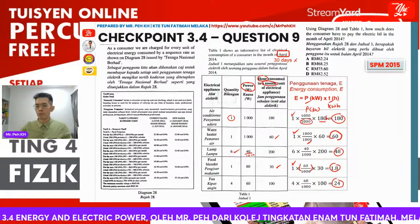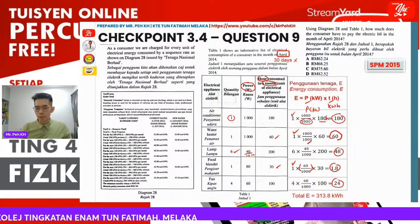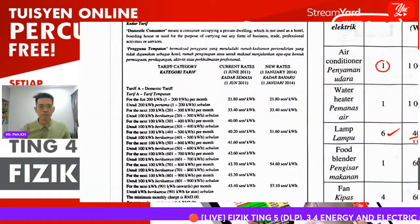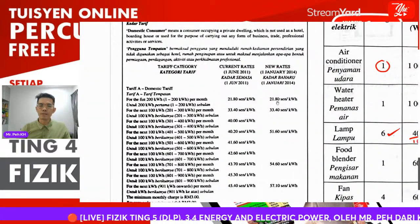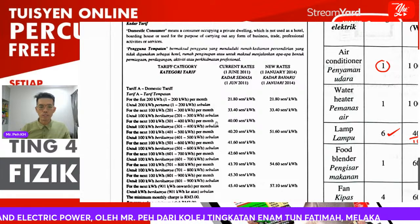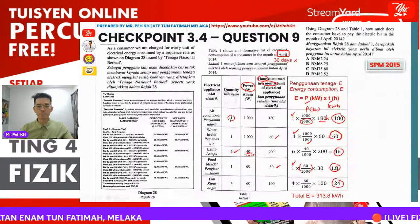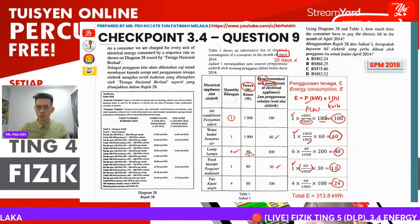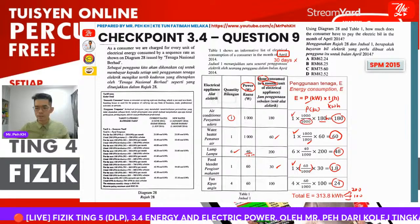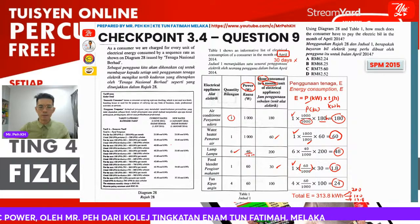So we add up all the energy in units of kilowatt hours, and we get the total energy use of 313.8. As mentioned, we have to follow the rate given here. The first 200 will use 21.80 cents. The next 100 will use 33.40 cents. And then the balance we have to use 40 cents, where it is stated as 301 to 400. So that means we have to classify it into 3 parts: the first 200, the next 100, and then the balance, which will be 13.8 for the third range.